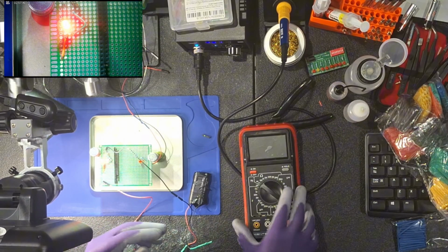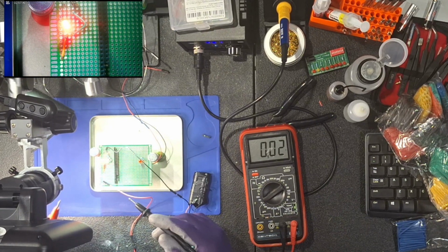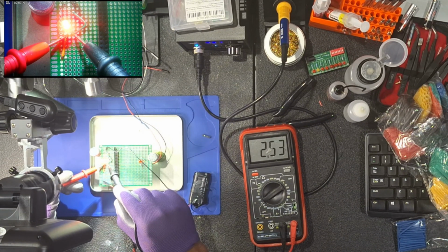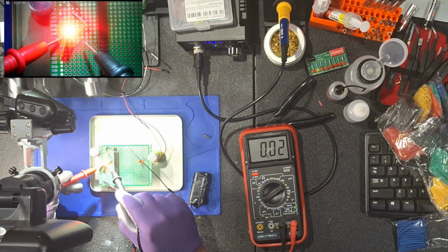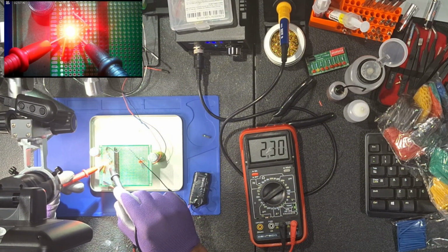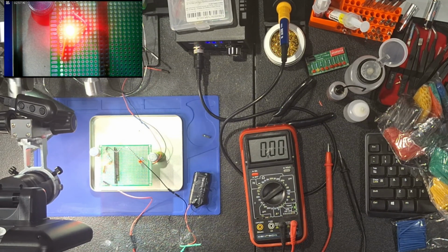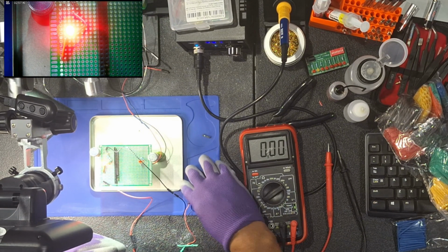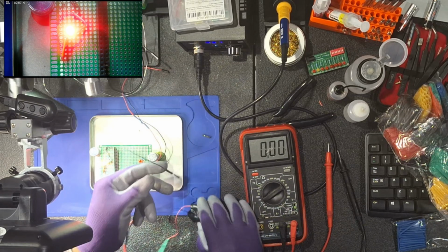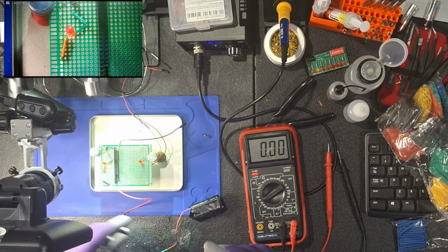The circuit is working. So now I'm going to do a quick test of the voltage to see how much voltage the LED is using. So 2.53. So it's getting even more than what the data sheet would say. And this is one of the things with LEDs, they don't have any resistance in them. So whatever you connect it to, it will just pull as much current as it can until it burns itself up. So the battery pack is safe. 3 volts is good, no damage.